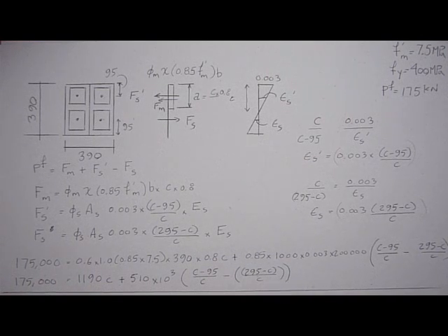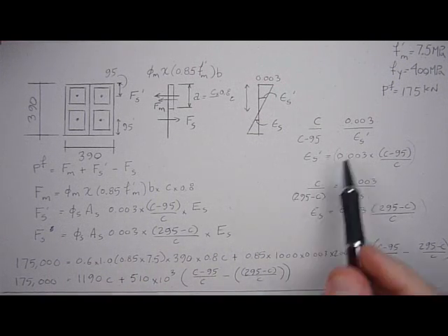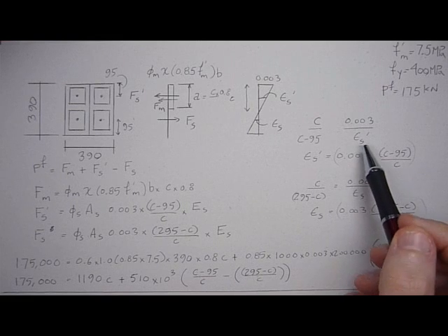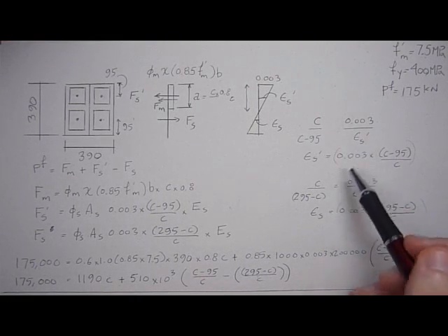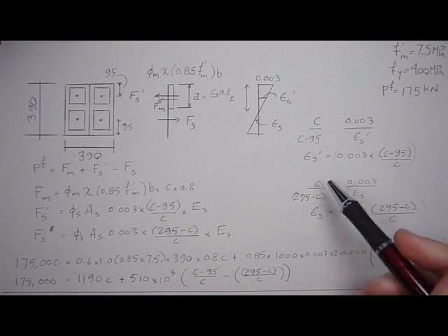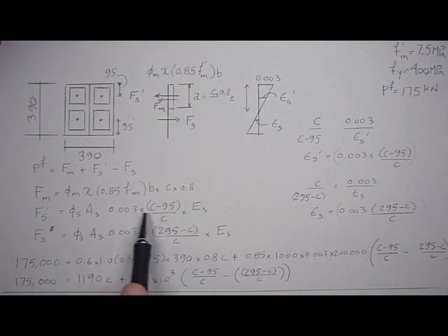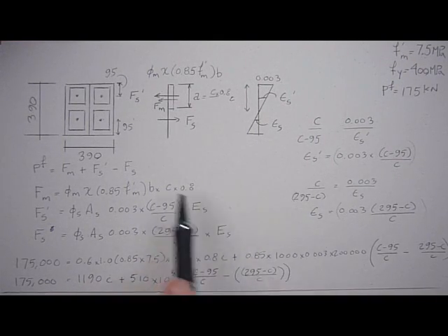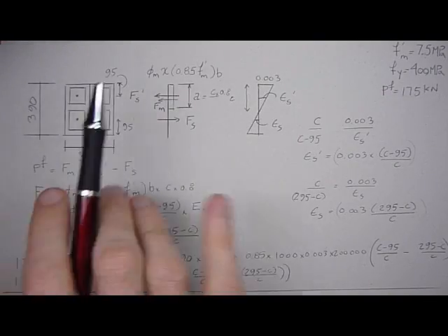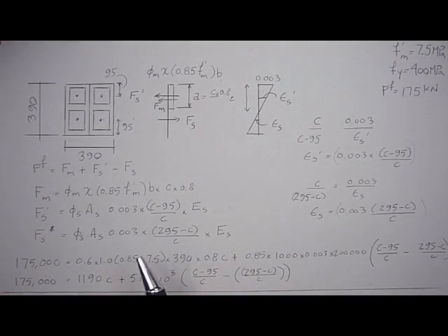So we'll stop right there for today, and then tomorrow we'll solve this equation for C, and then check that these strains are indeed below 0.002, which is the yield strain. If it's above 0.002, then it means that we could substitute directly in a stress of 400 MPa, which is the yield stress of the material. So we'll do that, and then we'll carry on and give this pier a height and determine amplification effects. Alright, so let's stop right there for today then.